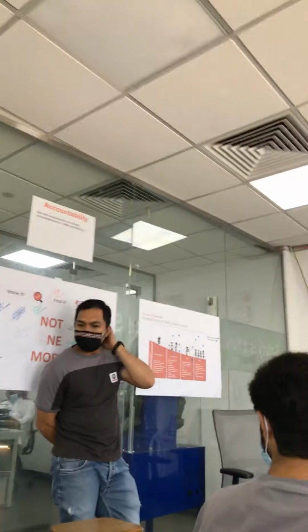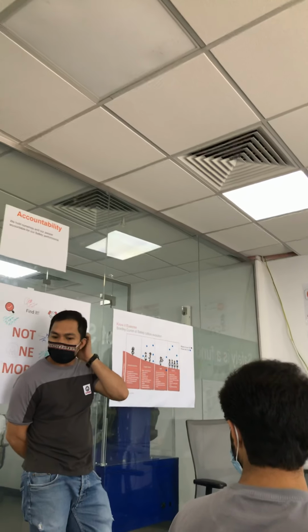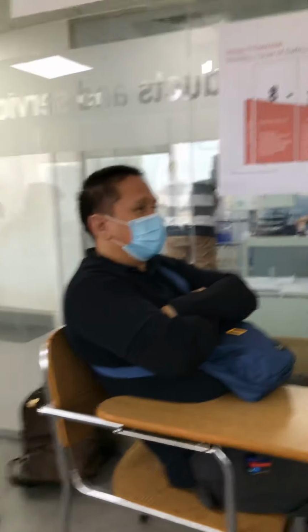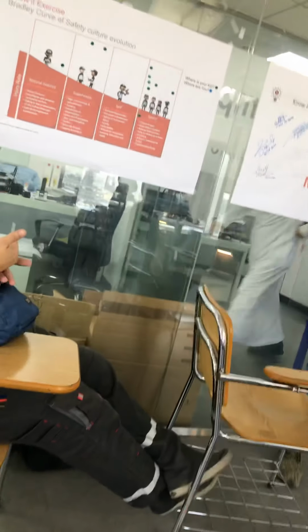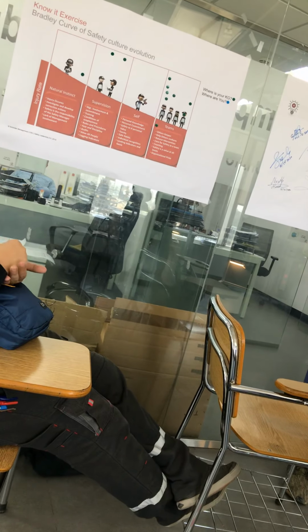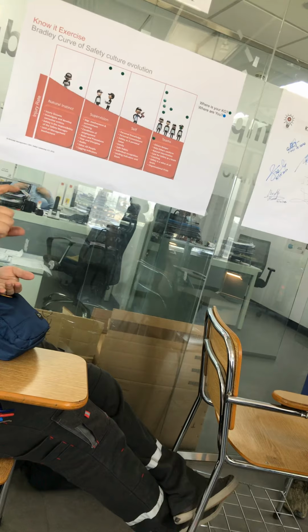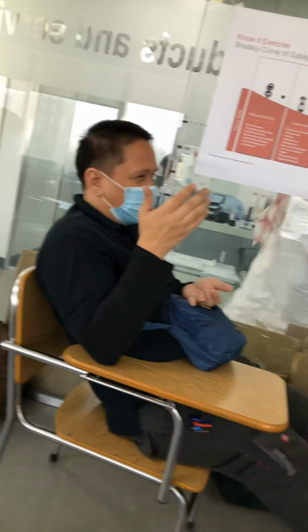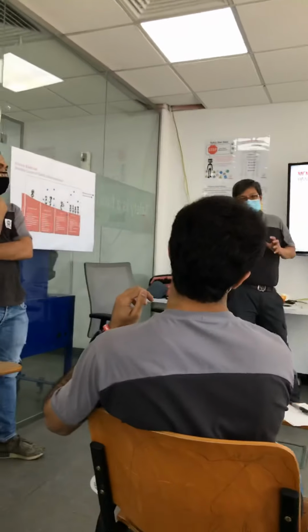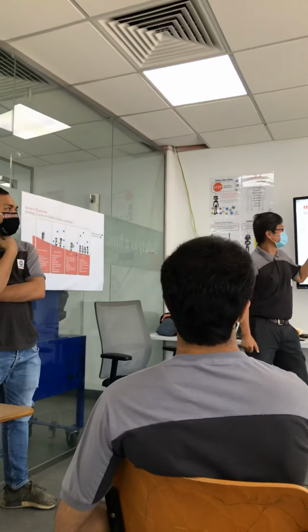If your elevator is machine roomless and they want to activate the safety gear, how are you going to trigger the overspeed governor? So with this device, when you press this one, there's a magnetic solenoid fixed on the overspeed governor. It will trigger the overspeed governor to activate the safety gear. This is the one.